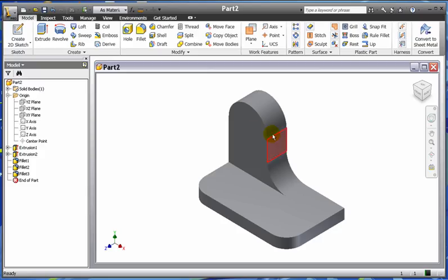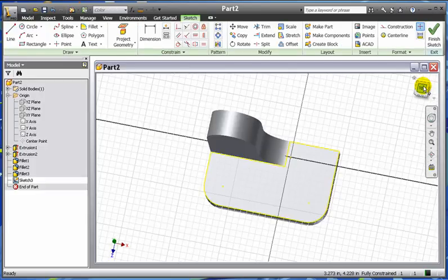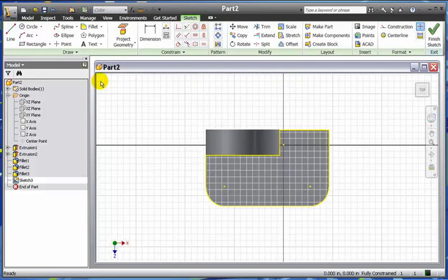We're pretty much done. Our basic shape is there. The only thing left to do is to make the holes, so I'm going to make the holes in the bottom here first. So I'll click here, make new to create a sketch. I'm going to go to my top view, and to make holes we're just going to use the point, and basically what this is going to do is we're going to say this is where the drill is going to enter the piece. So I'm going to click a point here, here, and here, because there's 3 holes in the base. And then I'm going to dimension these.